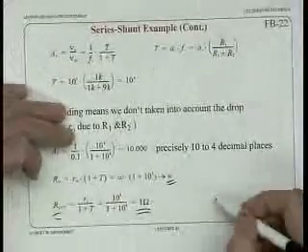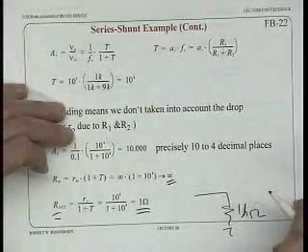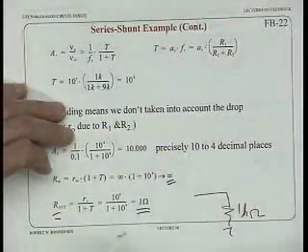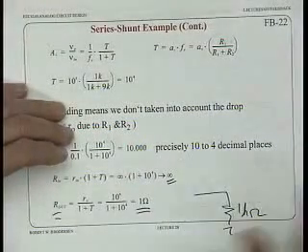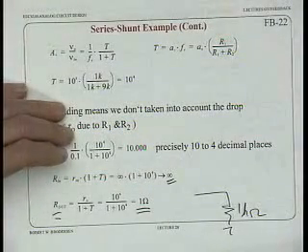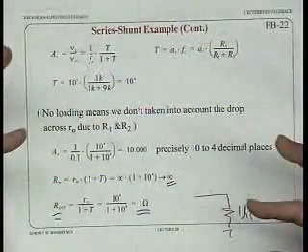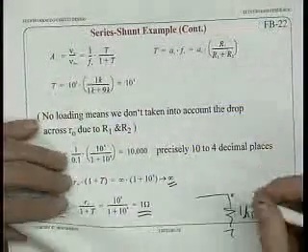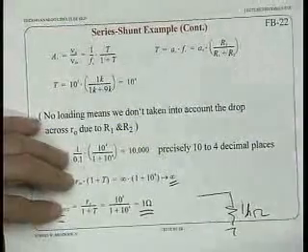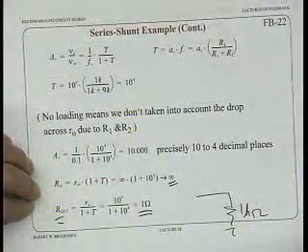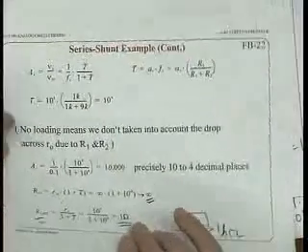So think about that. 1 ohm. Remember how tough it was when you've been trying to drive these 1 k ohm resistors? With this feedback, you'll have a 1 ohm output resistance. You could drive 10 k ohms or 1 k ohms with no problem at all. You could drive 50 ohms with no problem at all. So this feedback, in some sense, takes care of one of the big giant limitations we had in trying to make good amplifiers. Before, we can take the gain and turn it into really low output resistance so we can really drive something. So that's pretty neat, right? So feedback really is a very useful thing.